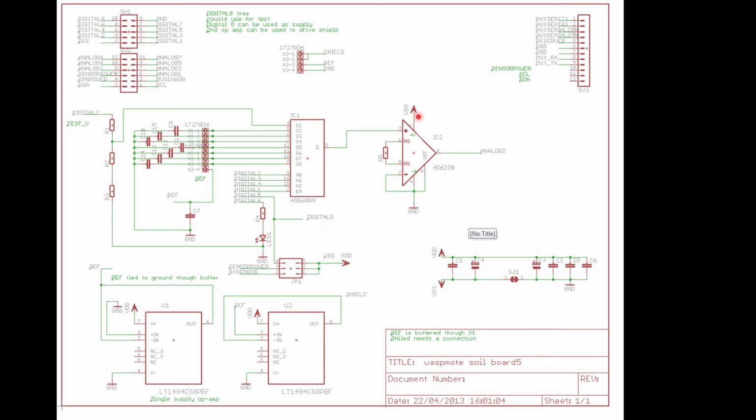We had to replace this in the end with a normal op amp, just to get us a range of operation. So we sacrificed common mode performance for normal amplifier performance, but that was good enough. We had to do it in the field as well, so we didn't have time to mess about with it when we got our circuit board.